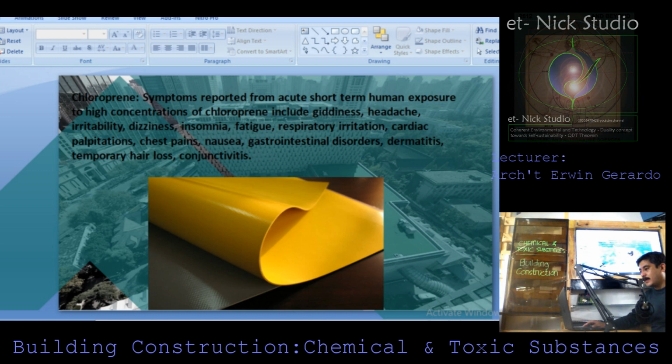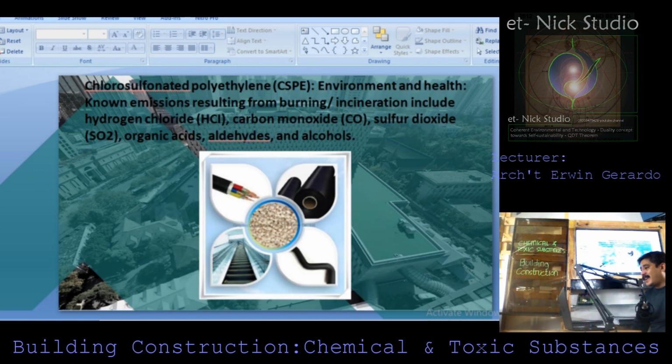Chlorosulfonated polyethylene, abbreviated as CSPE, environmental and health concerns. Known emissions resulting from burning or incineration include hydrogen chloride, or HCl, carbon monoxide, or CO, sulfur dioxide, SO2, organic acids, aldehydes, and alcohols.